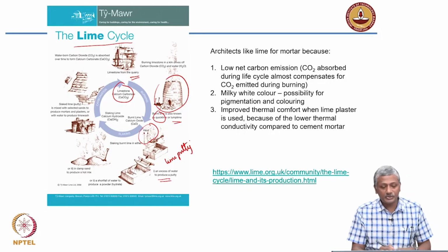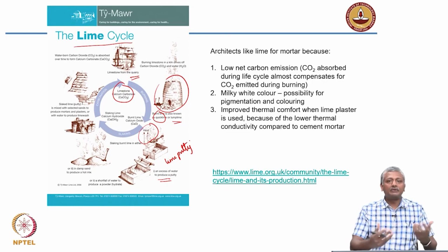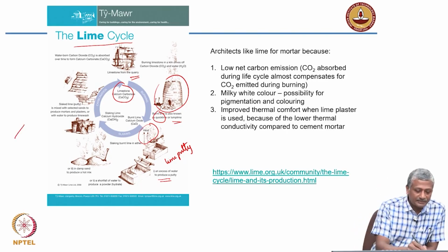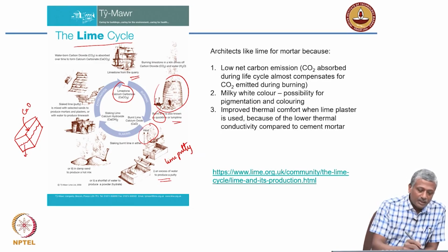So again, just to tell you a little bit more about the slaking process. In most large lime producing facilities, you will have rectangular tanks. You basically fill them up with water, and then you dump your quicklime into this water. With time, if you look at what happens here, I will just draw the cross section.